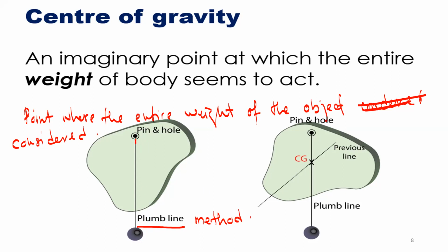So you poke the pin through the cut at any part, it is fine. Just poke through. Make sure the pin does not have too much friction with the cut. So the hole must be large enough so that the object, when it hangs, does not make the pin experience much friction. So it is like free. Let it hang freely. Then you see, it cuts straight through.